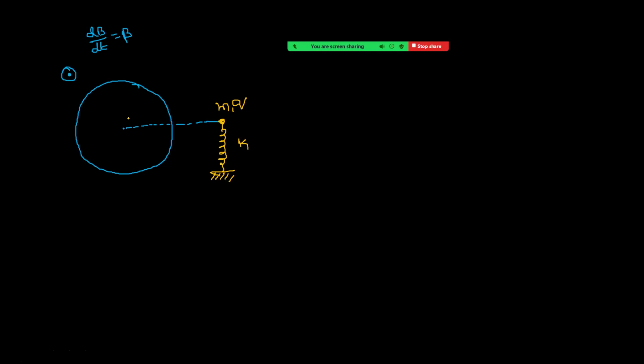Cross check once. If you imagine there is a conducting wire, a circular wire like this, whose center is on the axis. If you assume a conducting loop, and the field strength is increasing, then because of the induced current, the field direction must be into the board, right?